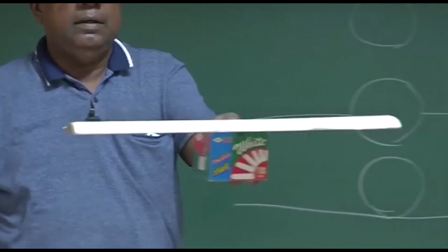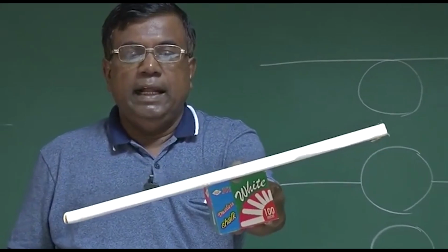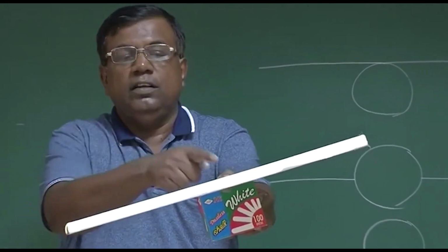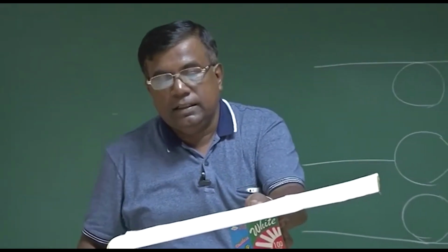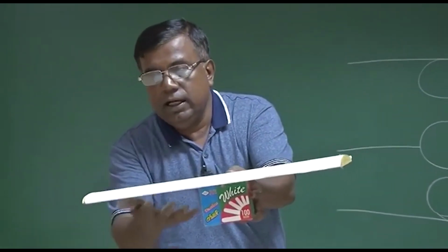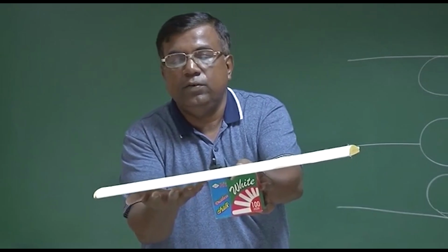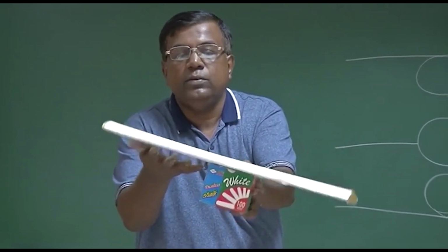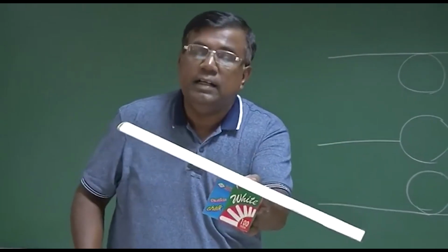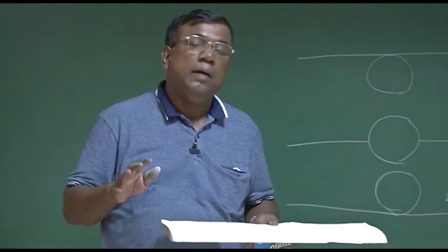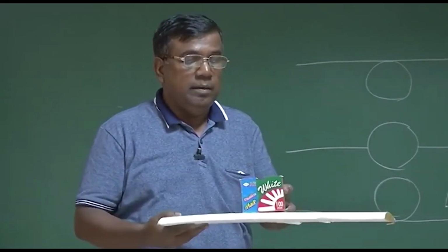This is typically, I am trying to represent a high wing case. Now, if there is a bank like this, what will happen? Because of this lift vector tilted now, it will try to side slip like this. As it side slips like this, air will gust in here, and that will give a pressure which will translate into force and moment, and will try to turn it back. So because of high wing, there is an initial tendency to come back to the original bank angle. So it provides lateral static stability.